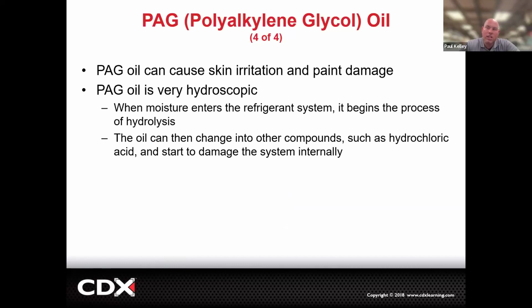But if a car, for example, is in a collision and the condenser's out of it and the lines are just hanging there for a month and it's been warm and cold and rainy and sunny and it's been exposed to a lot of moisture, that PAG oil is going to be absorbing the humidity because the system is not sealed because the lines are disconnected because it was in a crash. That could be a little bit problematic. That oil is going to absorb too much moisture. It's going to have some issues, and it can change into other compounds, hydrochloric acid, and start damaging the system. It's a mess. Cool.